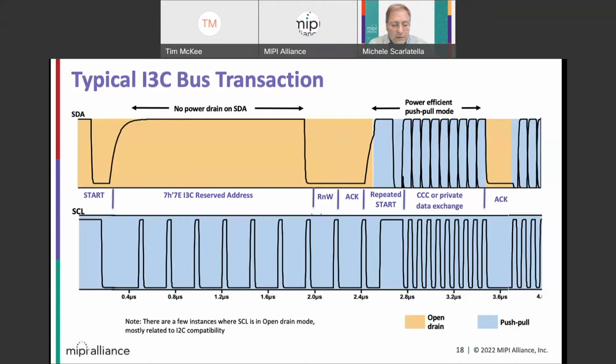This filter can also sometimes be present in I3C devices. Depending on the behavior of your application, you might choose to keep this clock very sharp, below 50 nanoseconds. This becomes completely invisible to the I2C, as long as the I3C devices can see it. So the idea is there. If you have I3C, you remove the spike filter, you can go fairly fast. And then when you go in push-pull mode, you move even faster.